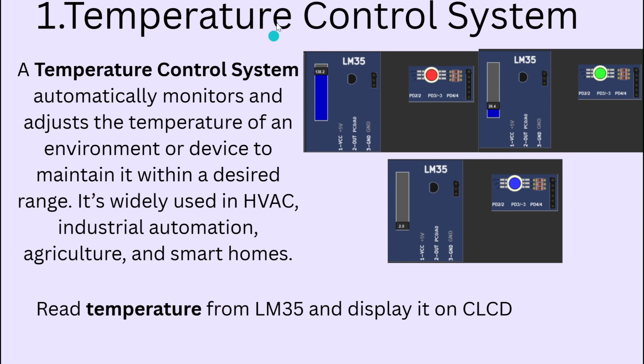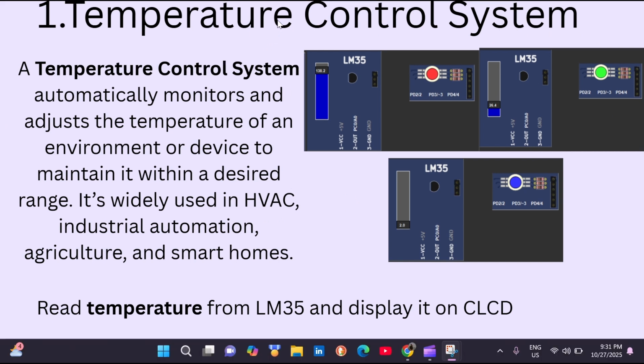My first project of this internship: temperature control system. A temperature control system automatically monitors and adjusts the temperature of an environment or device to maintain it within a desired range. It is widely used in HVAC, industrial automation, agriculture, and smart homes. Read temperature from LM35 and display on CLCD.